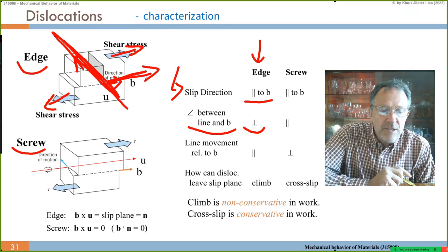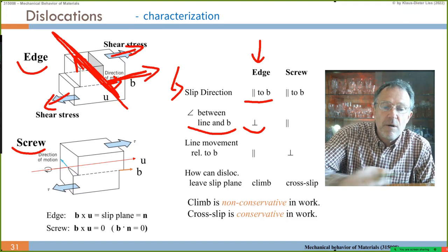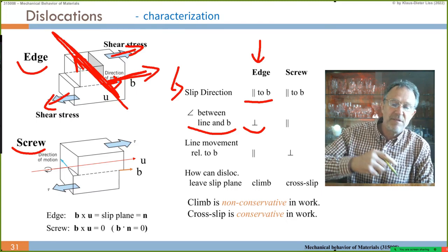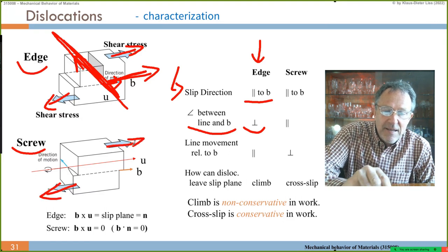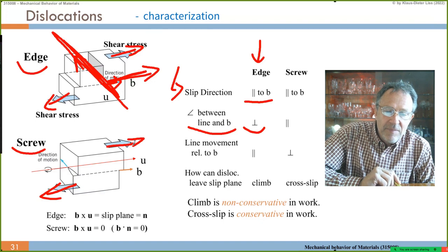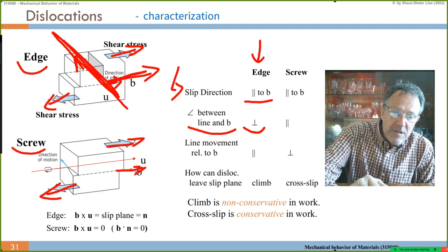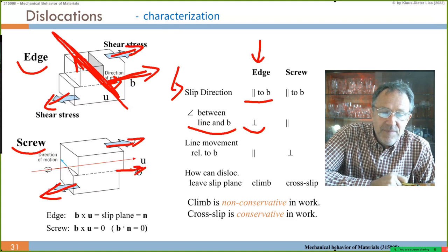In the screw dislocation, it works like a zipper. You open and close a zipper. You know that for the jacket or whatever, your handbag has a zipper. We apply the shear stress like this and like that, and the Burgers vector is along this shear direction.